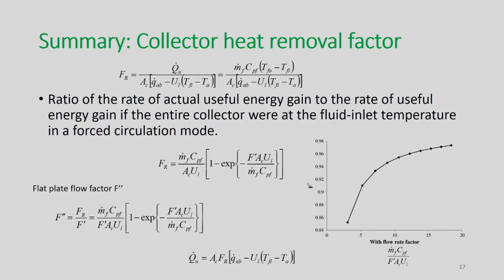So, if we summarize the collector heat removal factor, we have already defined how FR can be calculated. It is the ratio of the rate of actual useful energy gain to the rate of useful energy gain if the entire collector were at the fluid inlet temperature in a forced circulation mode.